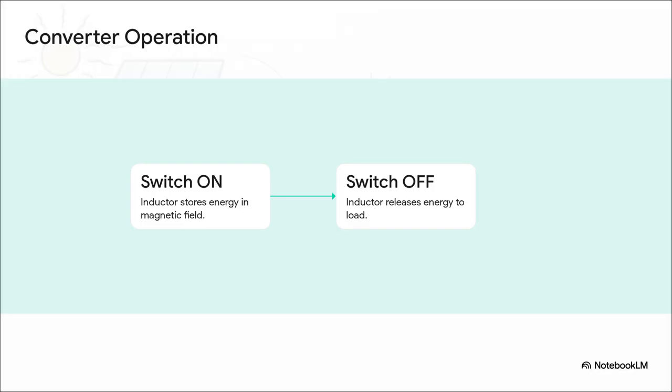And here's how that pump actually does its thing. It's a rapid 2-part heartbeat using a high-speed MOSFET switch, an inductor, a diode, and a capacitor. Step 1. The switch turns on. Power flows from the solar panels right into the inductor coil. But instead of flowing through the circuit, the inductor traps that energy, storing it as a magnetic field. It's kind of like pulling back a slingshot.